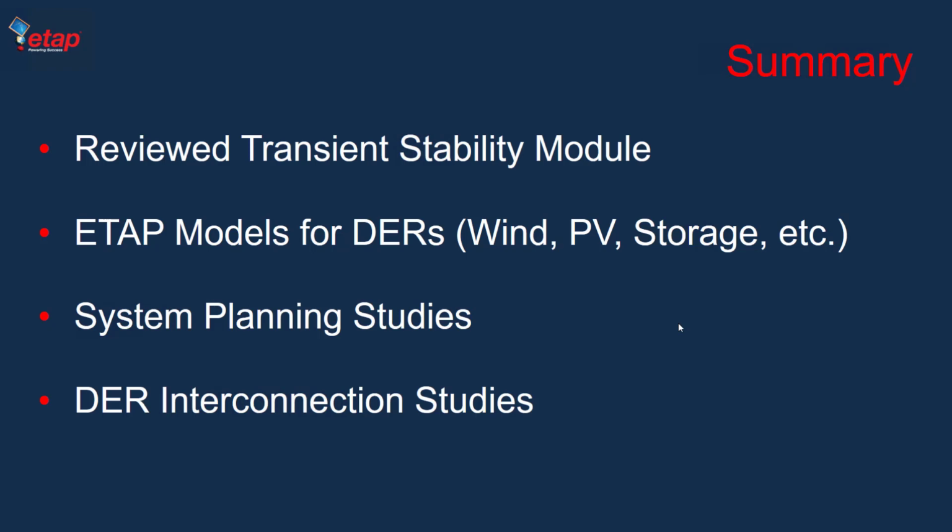The second aspect of doing a transient stability with DRs is the interconnection studies, where the focus is on the evaluation of a certain inverter technology or DR technology to make sure that it meets certain requirements, grid code requirements, standard requirements. Typically for this type of study, a vendor-specific model needs to be used, and we said that ETAP supports a concept of black box modeling.